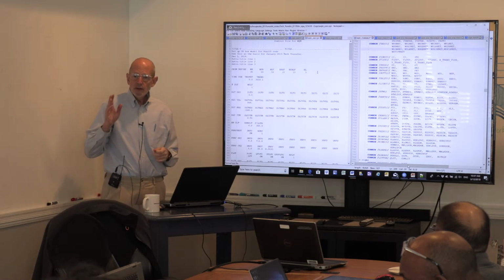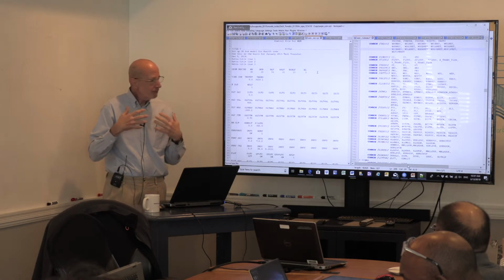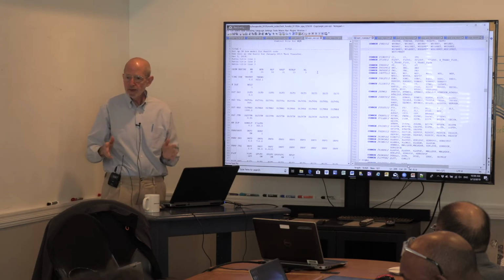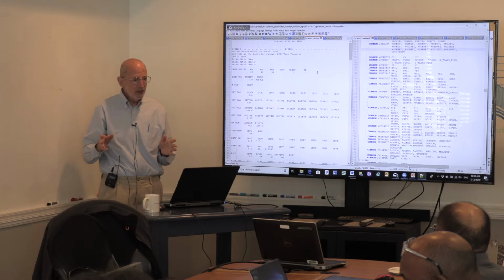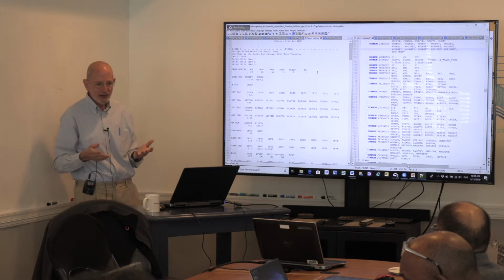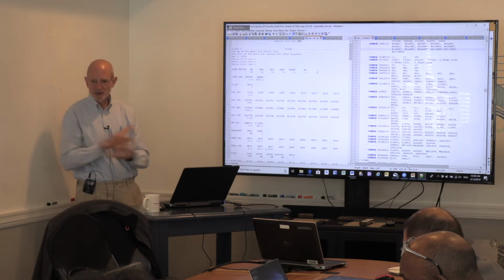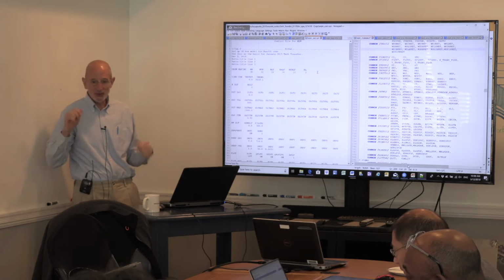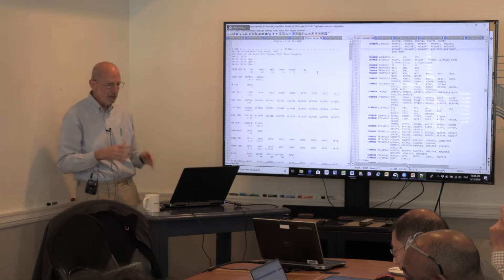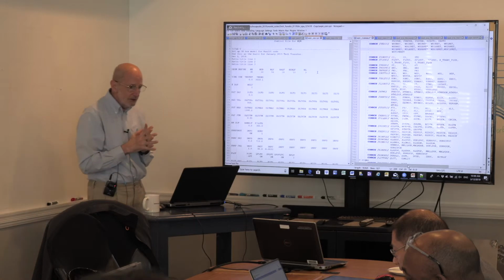Again, you have to have all of these lines in there. If I said I'd only need 3 title lines, I don't need 6, I'll just put 3 in there. It's going to bomb, because it's going to look for 6 title lines. So be meticulous. You have a blank line after.